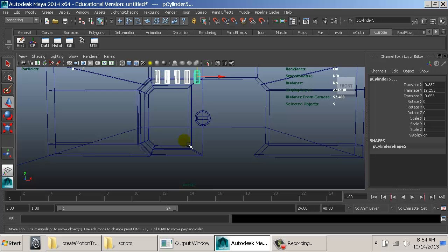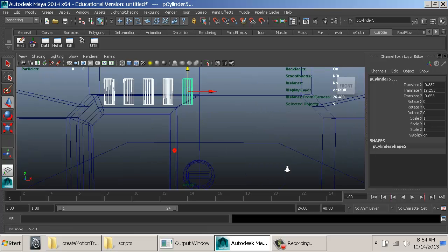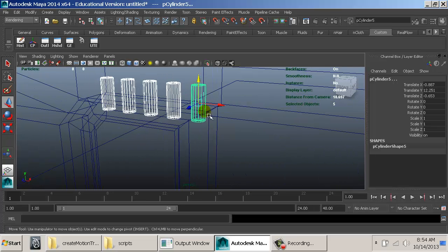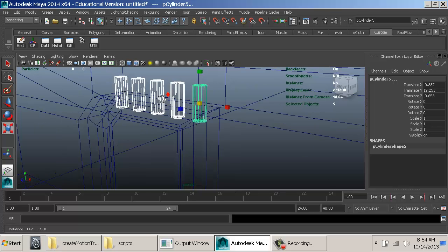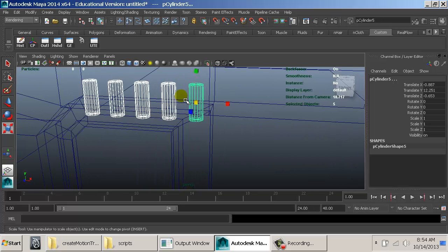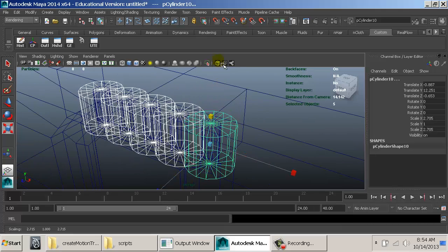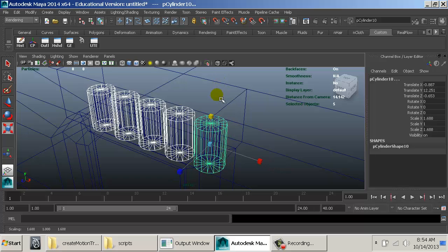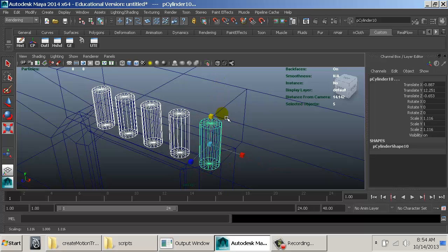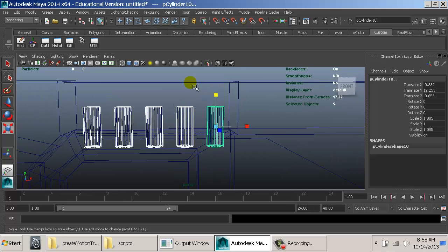They're also going to be on the bottom, so I'll have some more come up here. So what I want to do is duplicate these. These are the actual bars that are going to drop in. I'm going to duplicate these, and scale it up slightly. So I'm just going to hold Control and drag on this green manipulator. That way it just scales that out. I'm scaling it out slightly, just so the bars can drop in and have a little bit of wiggle room. And that's what we have.